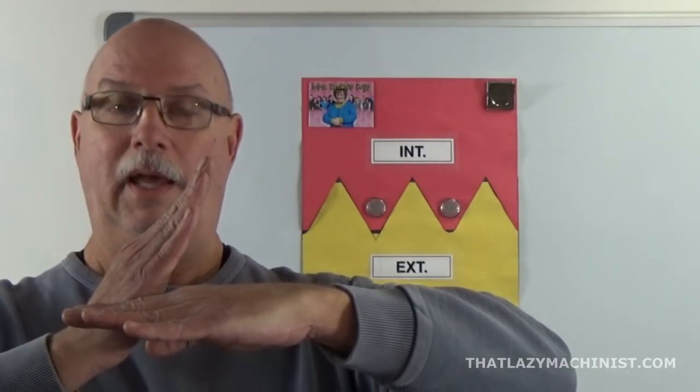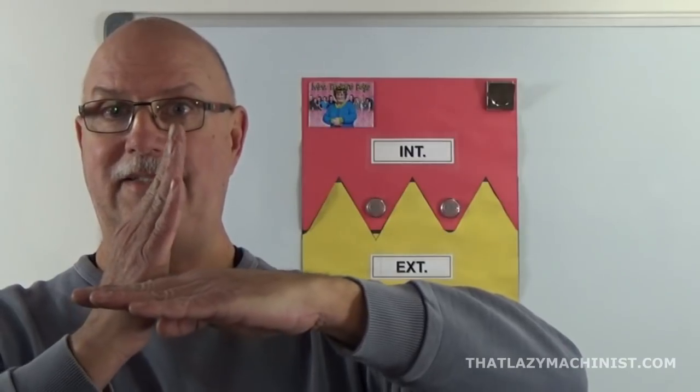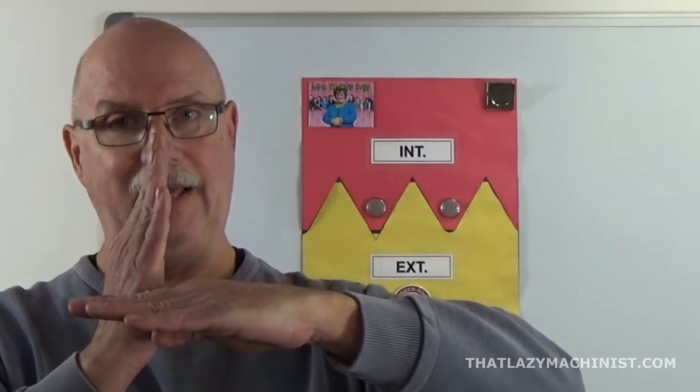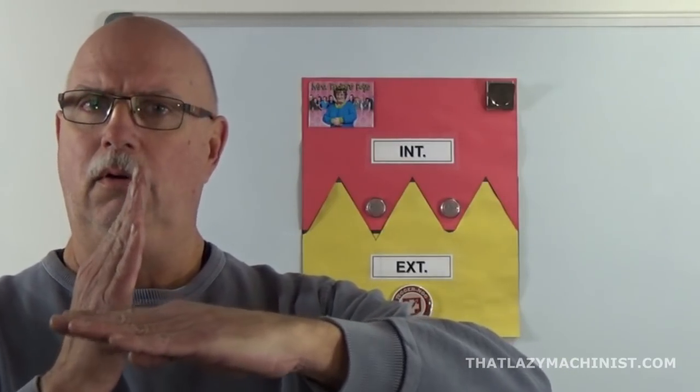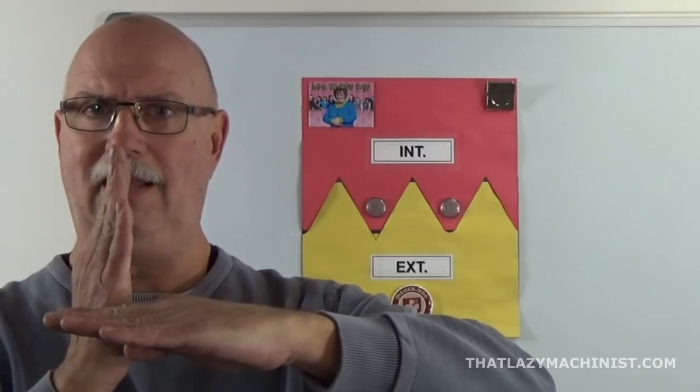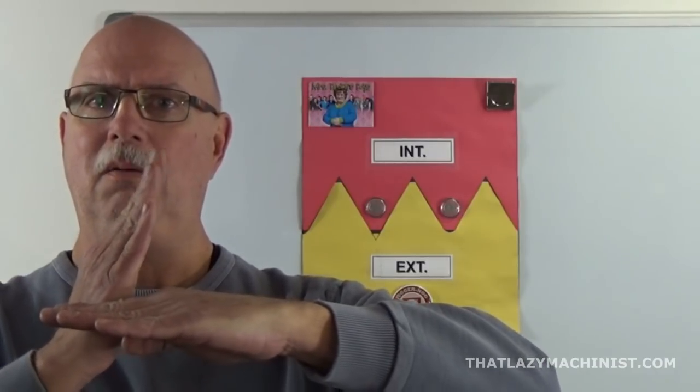And why? It's a question of helix angle. Now, if I have a 1/2 inch 13 thread, the helix angle is quite pronounced. And if I have a 1/2 inch 20 thread, the helix angle tends much more, but never gets there, but tends towards 90 degrees. So, more helix angle, less helix angle. What do you think? More helix angle is going to make a thread that is more prone to loosen by vibration. It's easier to unscrew.